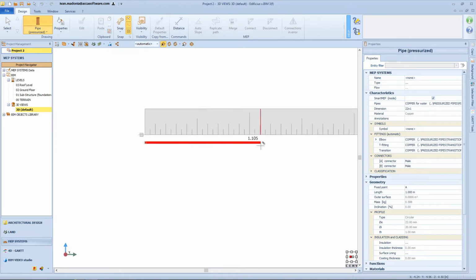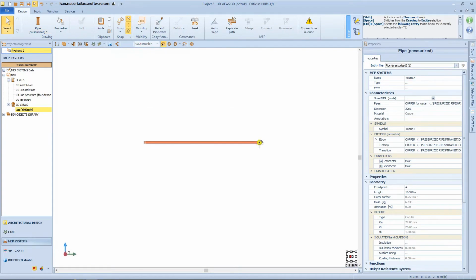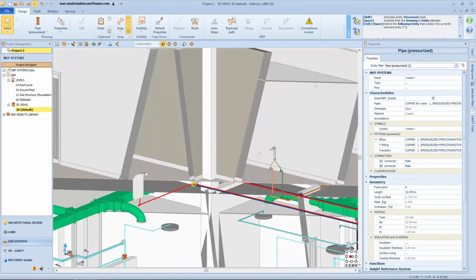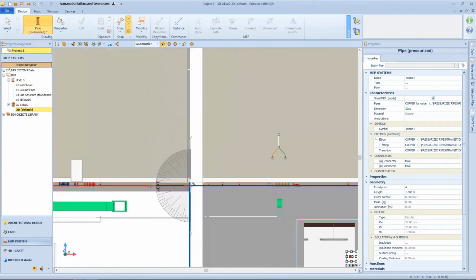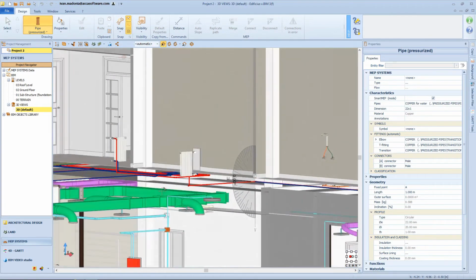You are always in the 3D view and you can trace the pipe according to the same steps seen previously, with the only difference that the view is that of a section plane parallel to the face of the cube activated and passing through the center of gravity of the attachment of the piping. Since this is a section plane, all objects present between the plane and our view will be excluded from the view. The section plane passes through the center of gravity of the pipe attachment, so the pipe will also be